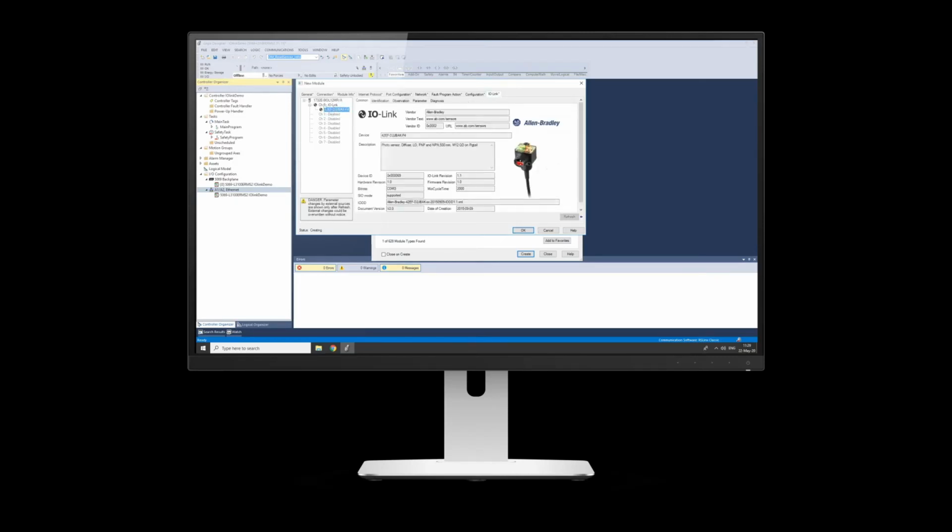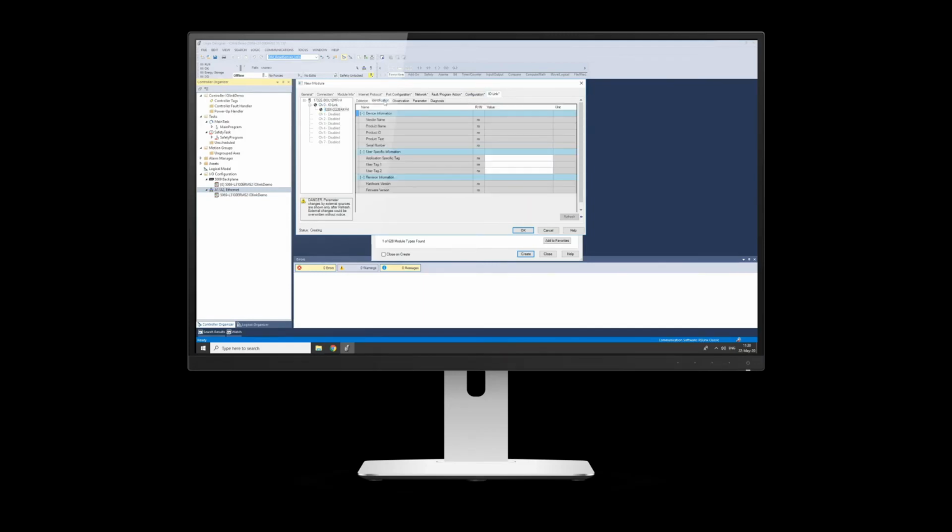You can then go back into IO-Link, click on there, and then you've got some parameters for that sensor already in here. You'll see there's some variables in here. At the moment, you can't do a lot of things, because these are actually what happens when it goes online. So we'll go online in a second and show you what you can do with these. But you can see they've got parameters that you can now set for the sensor directly through this window.